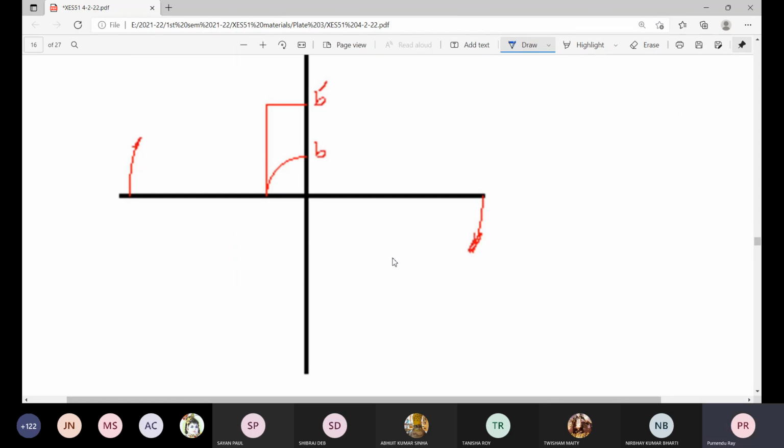Object is in second quadrant, but we need to open this space. So for that, this 90 degree movement about this line XY will give you the HP overlapped on VP, and there you get the 2D presentation of these two different views.